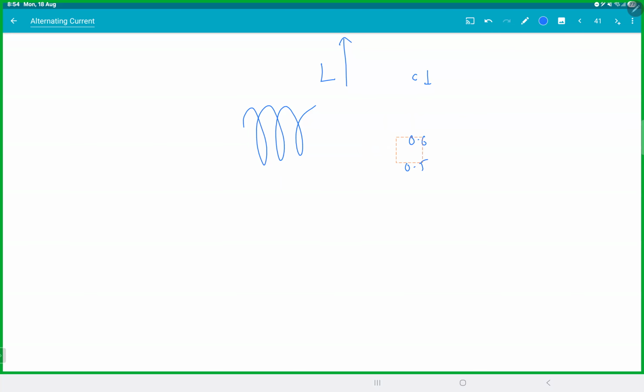So what this guy was suggesting is we will build a room full of capacitors and we will keep this room in series to your factory circuit. Thereby, we will improve the capacitance of the system and your power factor will go from 0.6 to 0.7 or 0.75. This will give you an efficiency of around 8 to 10% more. Now, in a factory, your electricity bill goes to almost 10 to 15 lakhs per month, depending on how big the factory is. And you can save 10% of 10 lakhs every month. That is 1 lakh per month. In a year, you're saving almost 12 lakhs. And it costs them 25 lakhs to build it. Within 2 years, they'll recover it. So the concept was right.